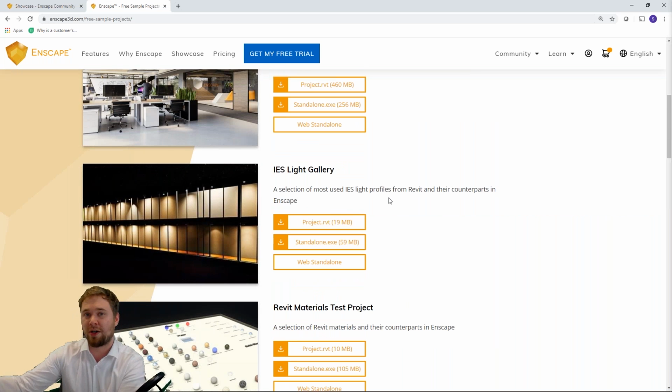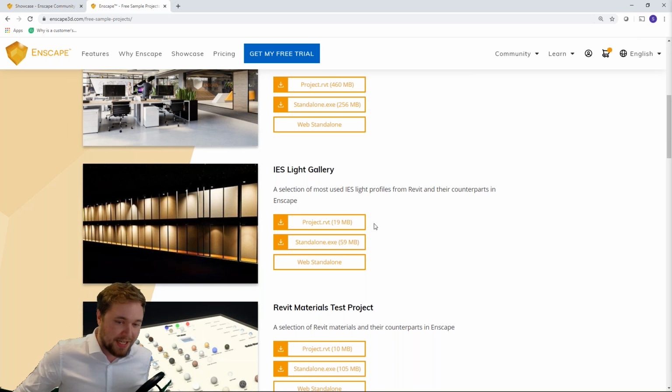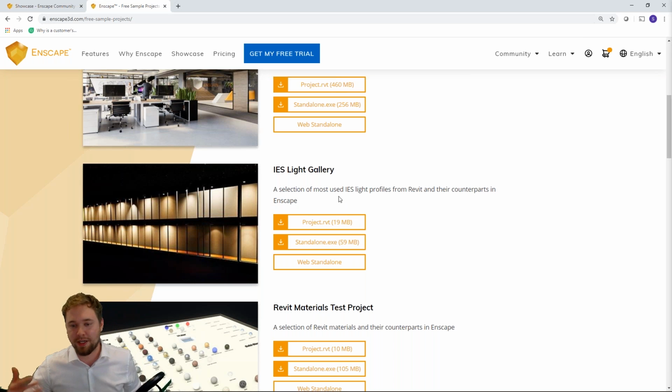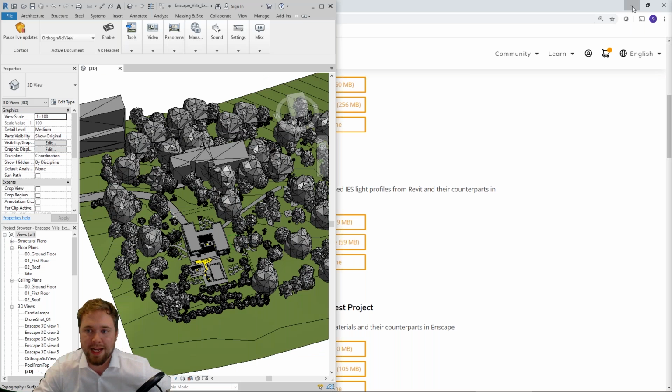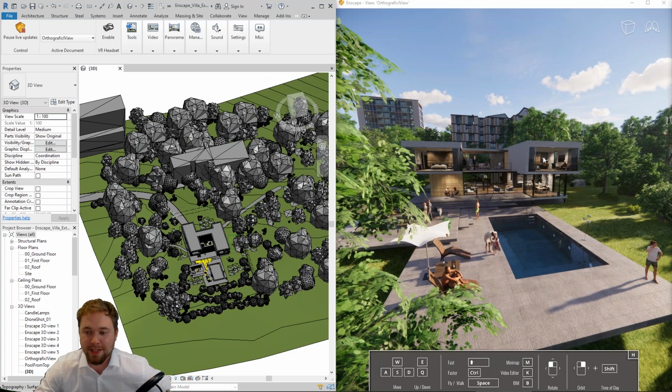It depends on what CAD software you're using. In Revit, you can just use IES web files the regular way, as you would handle it in a light fixture. In SketchUp, if you use a spotlight, you can check use IES light and load your file.